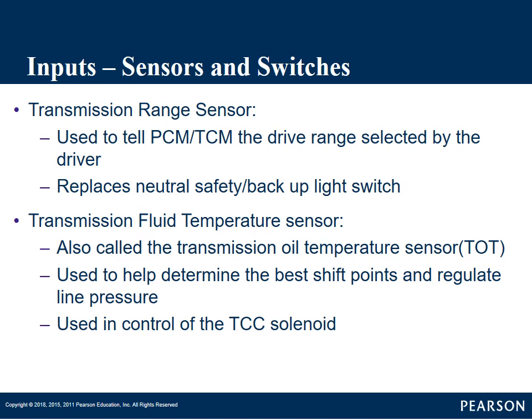These can also be called manual lever position sensors because it is monitoring the manual position of the shifter. Something very important on these, intermittent issues or codes in these can cause shifting problems.